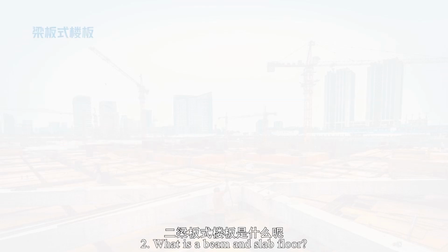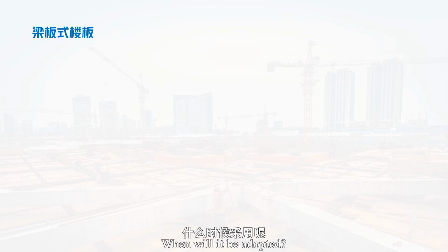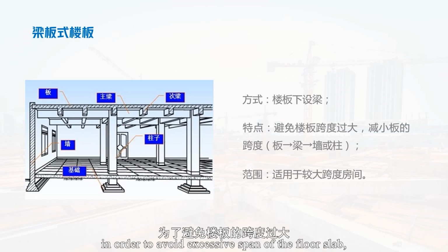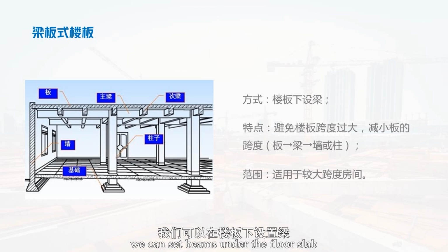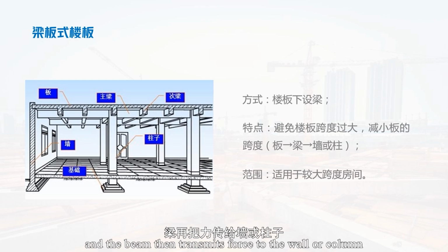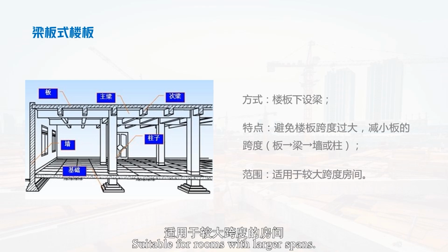Second, what is a beam and slab floor? When will it be adopted? When the floor plan size of the room is large. In order to avoid excessive span of the floor slab, we can set beams under the floor slab to reduce the span of the slab. Its transmission characteristics: the plate transmits force to the beam, and the beam then transmits force to the wall or column. Suitable for rooms with larger spans.